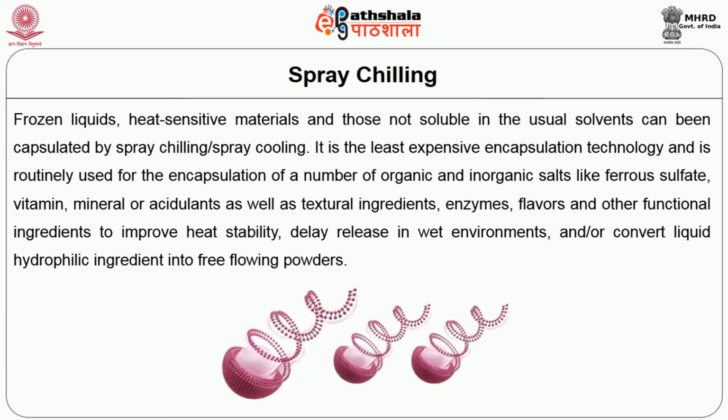Frozen liquids, heat sensitive materials, and those not soluble in the usual solvents can be encapsulated by spray chilling or spray cooling. It is the least expensive encapsulation technology and is routinely used for the encapsulation of a number of organic and inorganic salts like ferrous sulfate, vitamin, mineral or acidulants, as well as textural ingredients, enzymes, flavors and other functional ingredients to improve heat stability, delay release in wet environments and or convert liquid hydrophilic ingredient into free flowing powders.